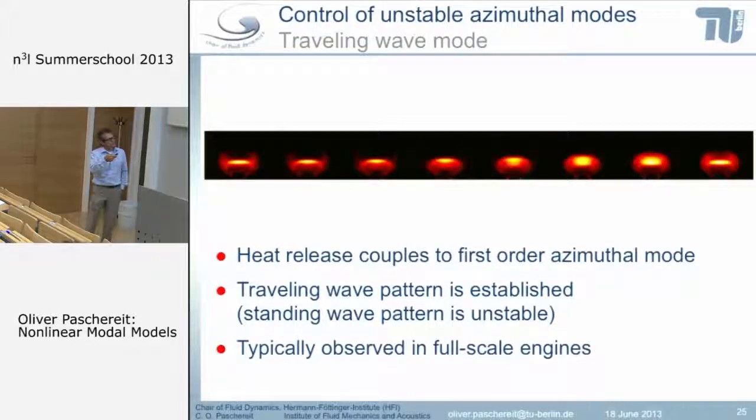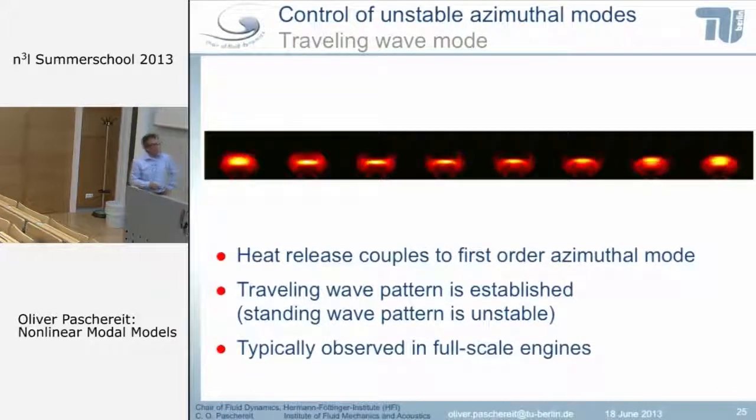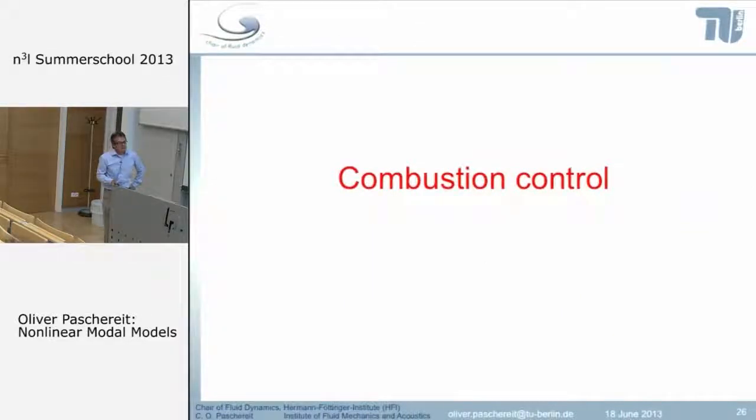And this shows you how this flame responds and so on and so forth. So this is what you typically see in full-scale engines. So the standing wave pattern is unstable, but what you generally get is a moving mode around the circumference.